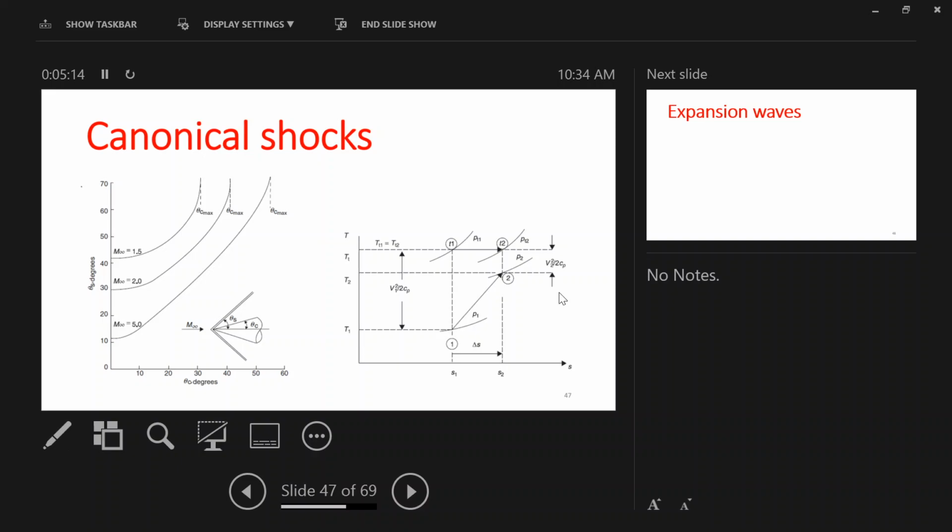Does that make sense? Which essentially means that you are going to have, what does that mean? Let's brainstorm here. As you approach infinity, your shock angle is going to keep growing. But what does an infinity angle mean? A normal shock. Is a normal shock a shock wave with an infinity angle? It is 90 degrees, right?